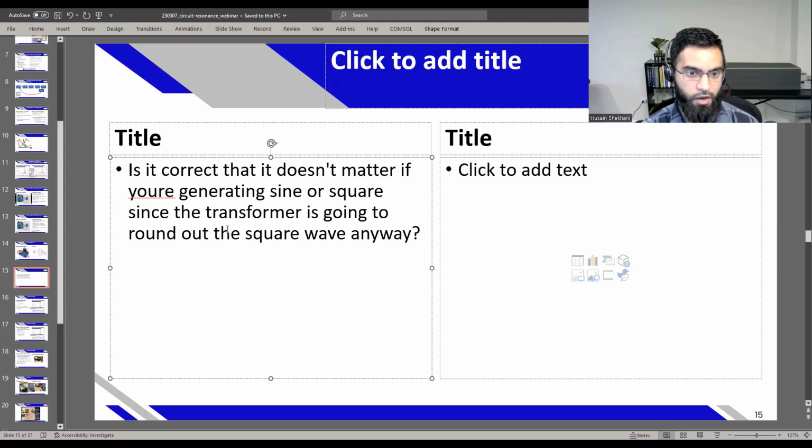But I was hesitant on putting those filters at the clock generator output, because I was wondering if it doesn't like to draw a lot of current. It likes to be driven into a high impedance load. So I didn't want to break it the night before I was making the circuit and everything. And the nice thing about using a sine wave is that it's easy to analyze the output. You don't get all these other harmonics on the output, and then it gets confusing to analyze.